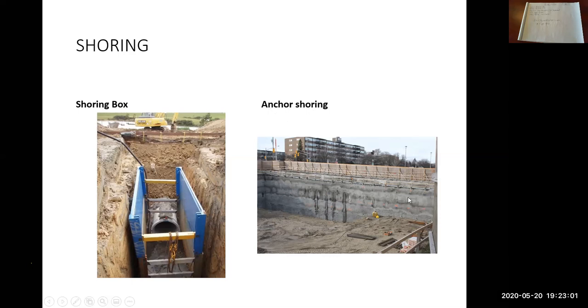So this is anchor shoring. So this would be your shotcrete wall type system. So shotcrete meaning it's concrete, but it's blown out of a hose, so using pneumatic or air pressure. So it's shot onto the wall.